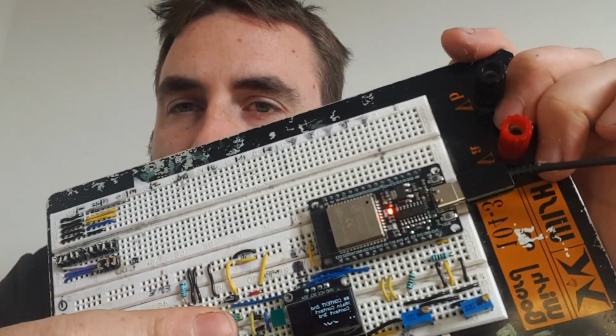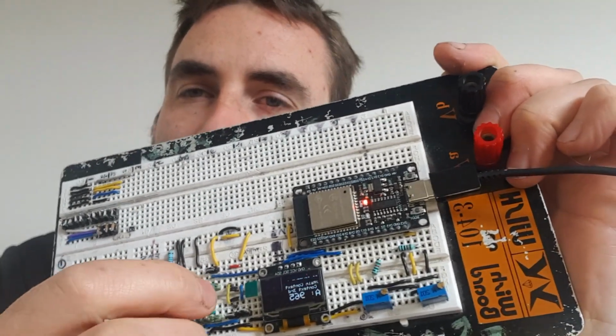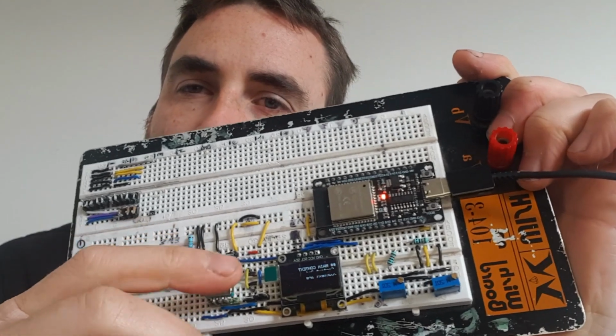In conclusion, it's not actually that hard to make a hardware user interface, and using a rotary encoder switch is an elegant way of providing user input. Now, one of the most difficult things about making a hardware user interface is actually packaging it appropriately, as you have to take into consideration dust and moisture in the environment in order to protect the hardware. 3D printing has helped with this issue somewhat.